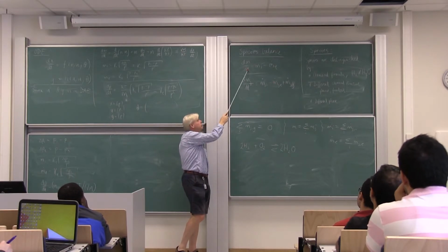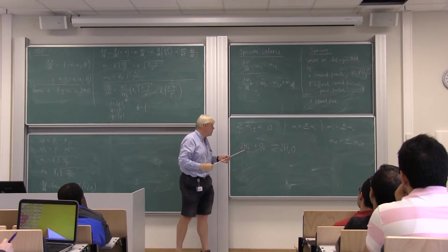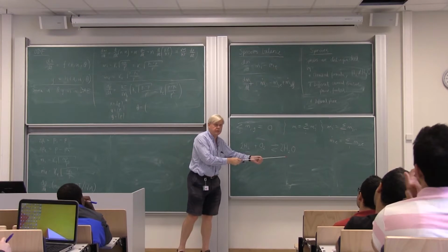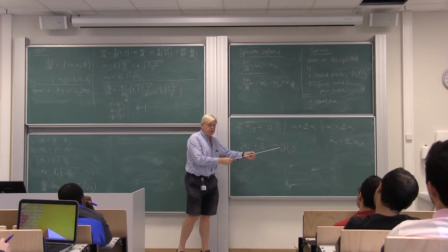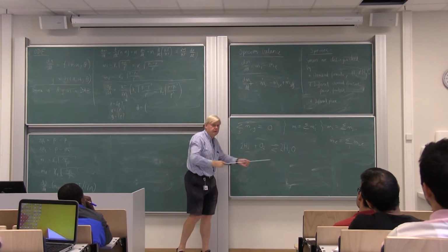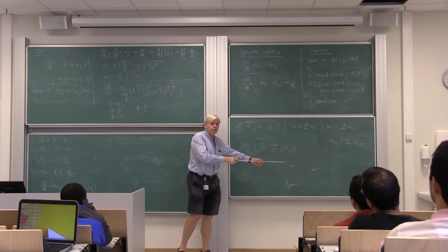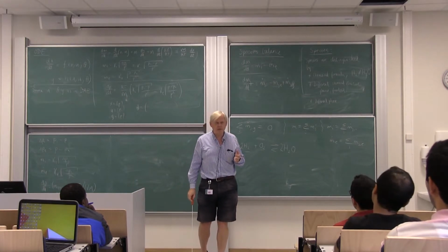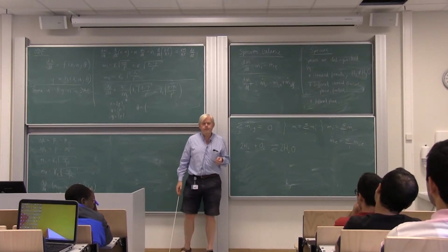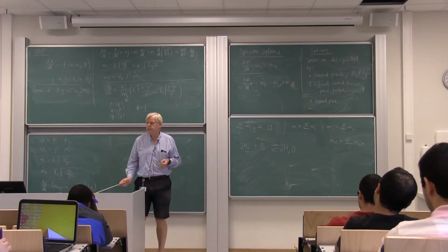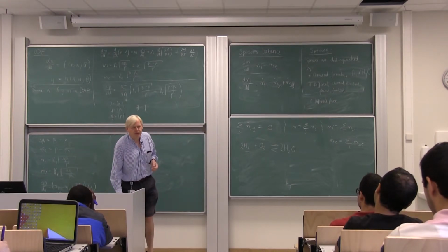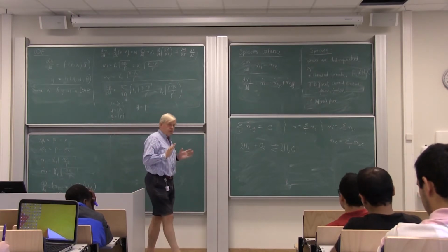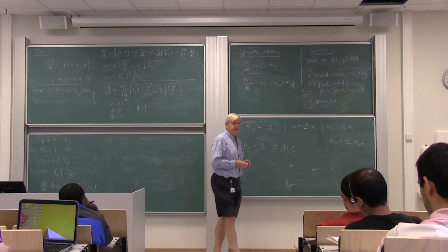So we can use total mass balance and then species balance for hydrogen and oxygen, or hydrogen and water, or oxygen and water. But we cannot use total mass balance plus species balance for all 3, because then we have 4 equations and we really only have 3 independent equations. Okay, but it's very common to use total mass balance in combination with species balances, and then we use 1 less species balance than there are species.